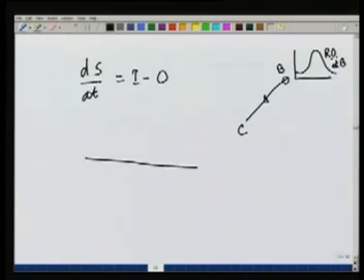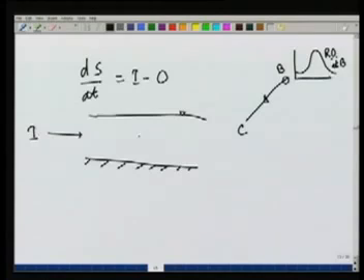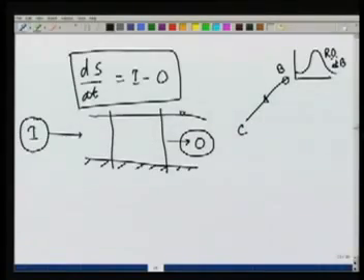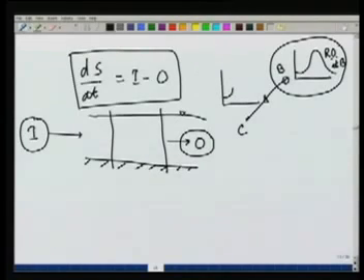So if we look at the stream, there is water level in the stream and there is some inflow. If we consider a section like this, there will be some outflow. And the continuity equation tells us that dS/dt would be equal to I minus O. So when we are routing the flow through the channel, what we need is the outflow for any given inflow. So basically, given an inflow hydrograph like this at point B, what would be the outflow hydrograph at point C, which may be something like this. This is what we need to find out.